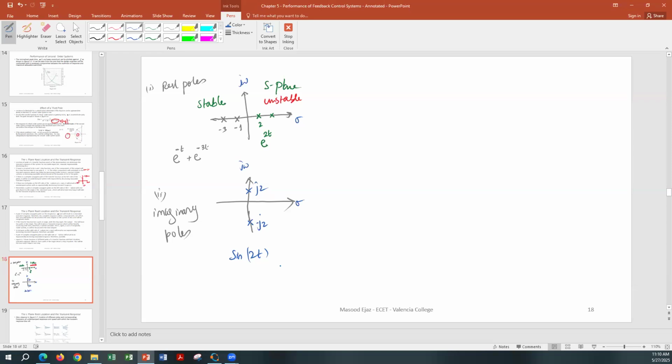So in this case, we call the system a critically stable system, and based upon the input we can decide if the output will be stable or unstable. So from the transfer function, the system is called critically stable, not stable or unstable, if your poles are located on the y-axis or j omega axis. So this is a critically stable system. And we're going to do some examples.